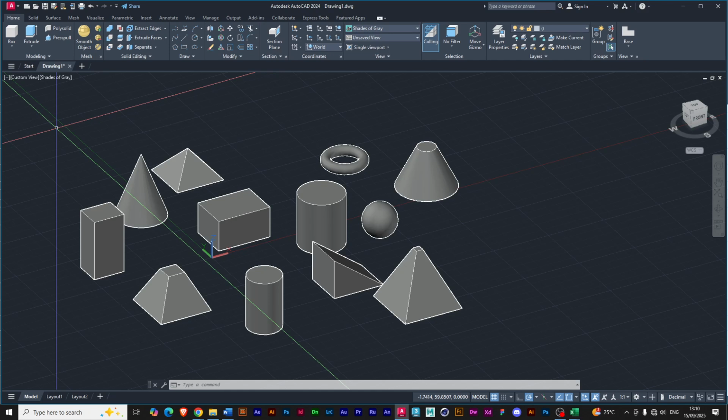Are we good? Can I go on? Okay. So we did the normal selection of clicking the object. AutoCAD has the window selection as well, which makes you select using the marquee, but there are two marquees. There's a blue and a green marquee. Clicking and dragging to your right creates the blue marquee. To your left is the green marquee.